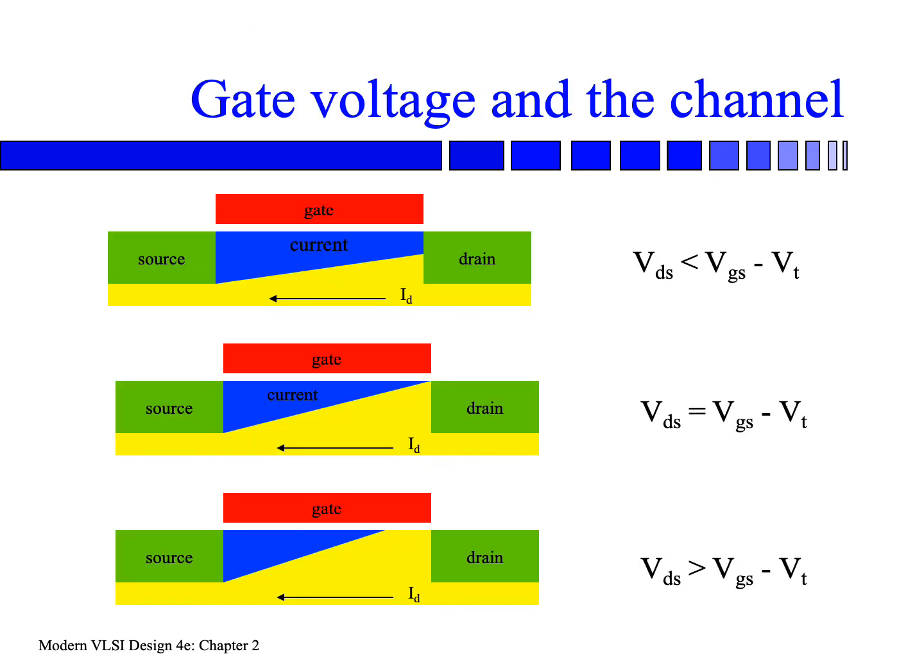Here I just recap what we have learned in the last lectures. Remember, we talked about three regions. We have the linear region, which is the top part of this figure. Basically, in this linear region, the gate voltage is larger than both the source and the drain. As a result, we have a channel formed underneath the gate.